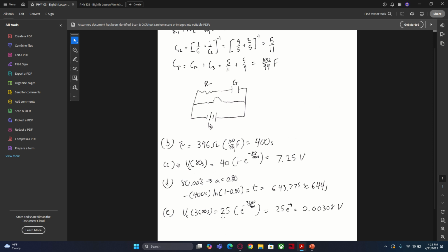V0 is the voltage across our capacitor right at the moment that we start discharging it. That could be equal to the battery supply. If you see in your problem that it says that the capacitor was fully charged, basically, that means that we're assuming it was charged so that the voltage difference equals the power supply, VB.